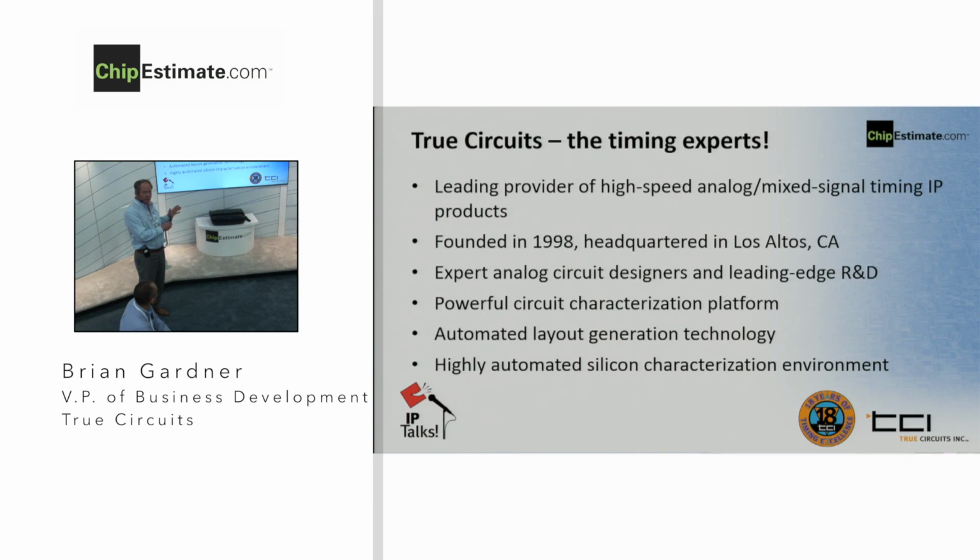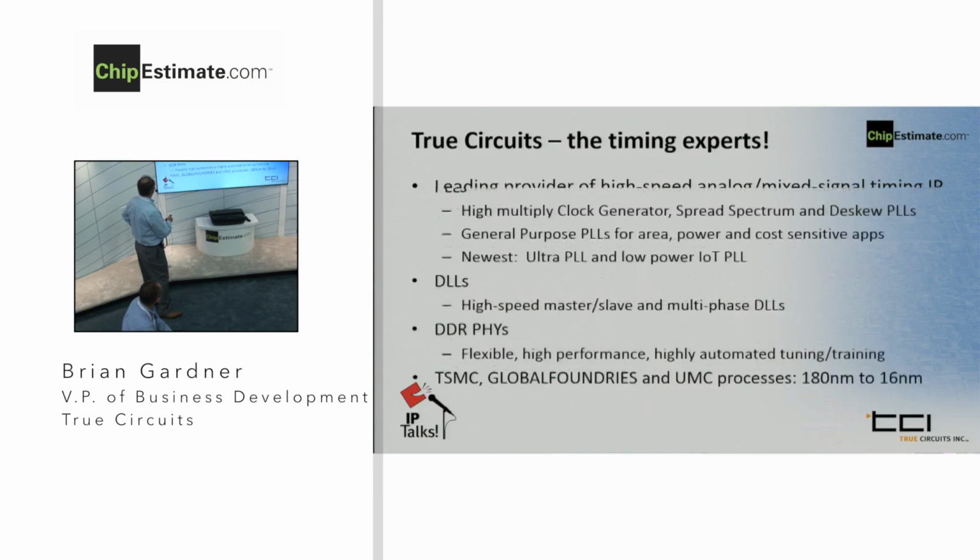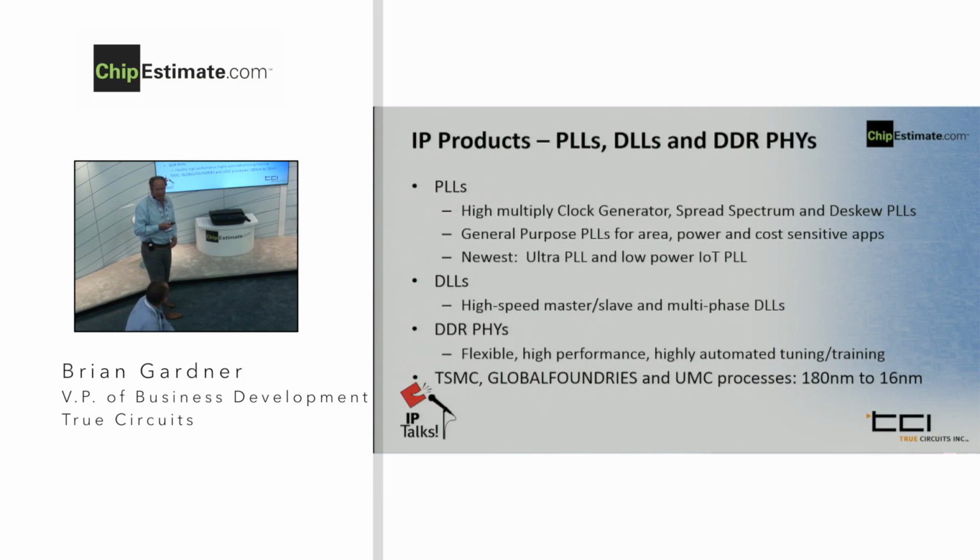So when we go to another node, we take our entire portfolio, put it on one test vehicle, run that, 5-way split, minus 40 to 125, and then all that data is collected automatically. We create a report automatically. And then our goal is not just to meet spec, but to close the loop that SPICE predicted it should work like this, and it does work like that. So that allows us to have a fairly diverse portfolio.